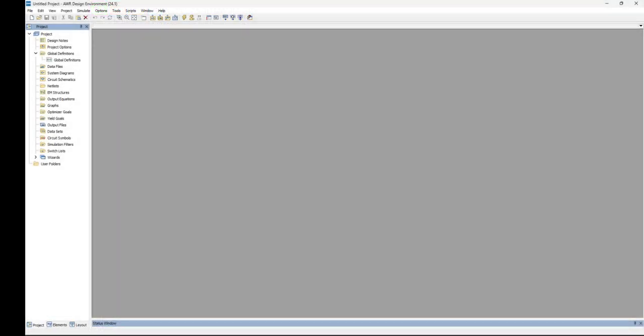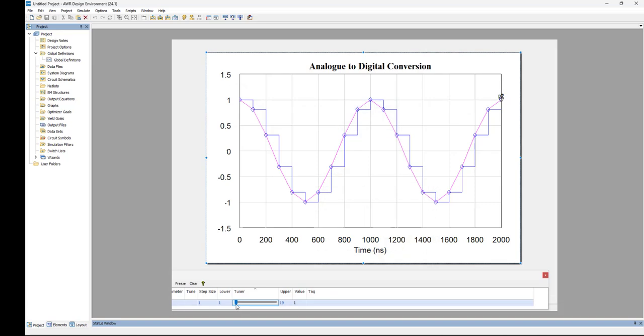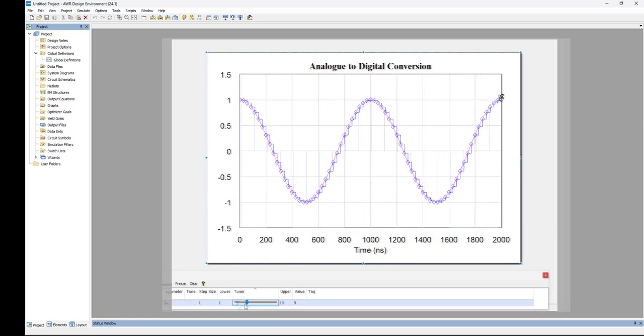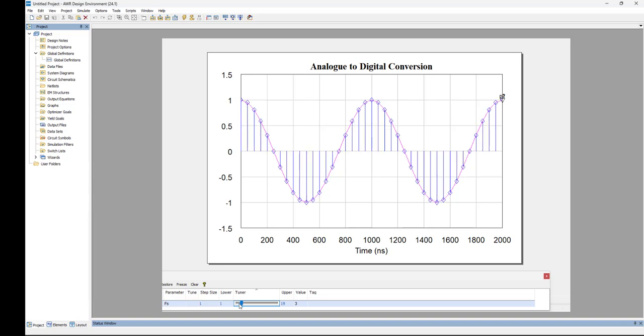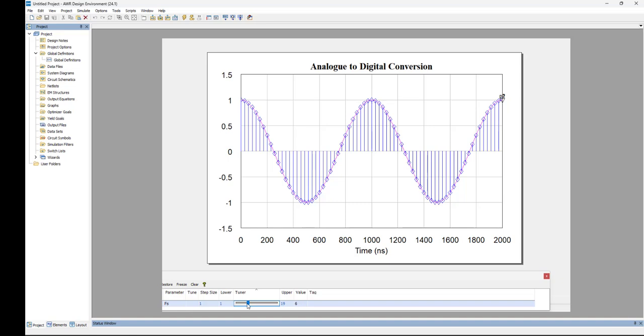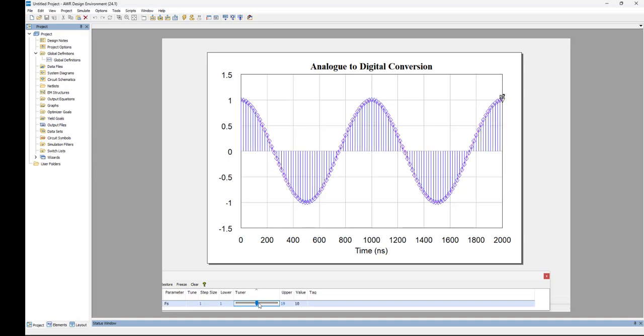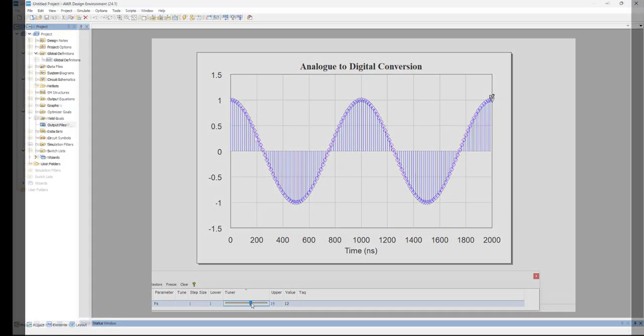In any digital system, continuous signals are sampled using an analog-to-digital converter, ADC for short, and that's unavoidable. Digital communication systems are no exception. Indeed, VSS models realistic communication systems, and this is why it is a sampled, time-domain simulator that uses a fixed time step between samples. So when we generate a sine wave in VSS, depending on how we sample it, we may end up with very different graphical representations.